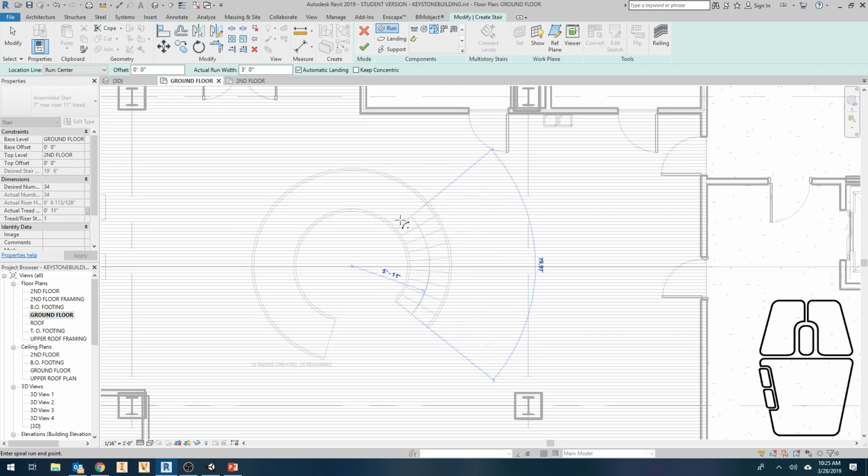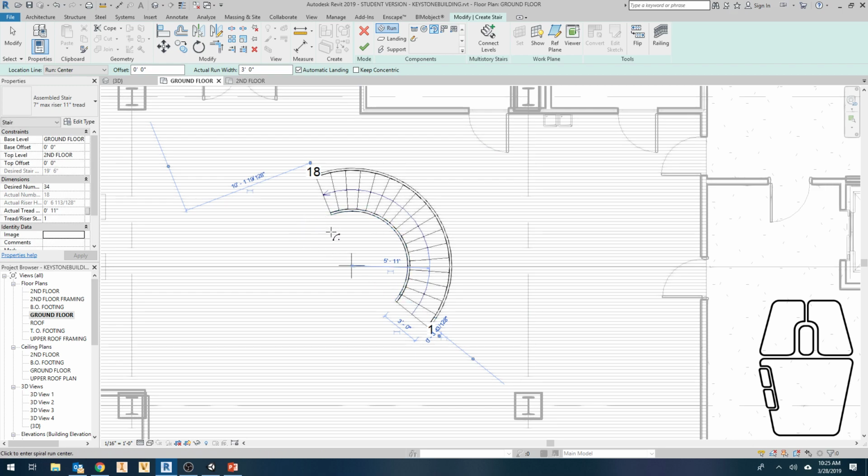Oh, this one lets you decide how many risers to put and where. The other one was automatically creating all of the risers in the space that you created. You see that, how I did that? This one's letting you decide how many risers to put and where. So let's put like the risers to there, right? And then click here. See how it tries to make a landing? You see how it's like making a landing there? Or thinking about it anyway? Let's do, I don't know, that.